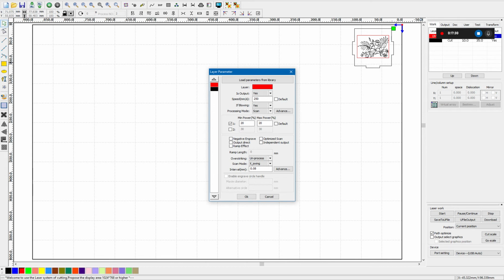The next setting is the interval, or change in Y position between X scans when running in X swing mode. We generally leave this set to 0.08 mm. The laser beam is wider than this, so there is a bit of an overlap, but we found it gives smoother looking results than setting the interval to 0.1693 mm, which eliminates any overlap between the scan intervals.